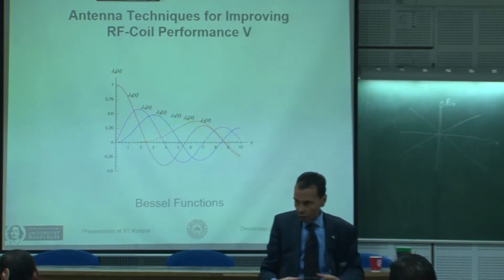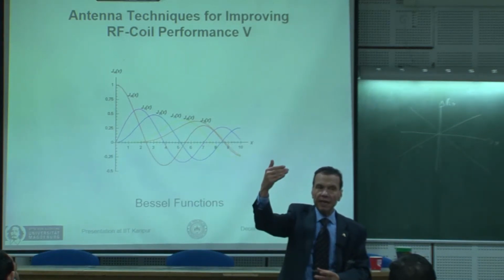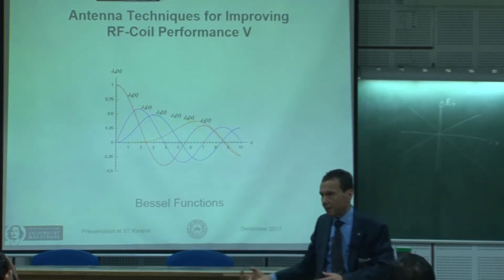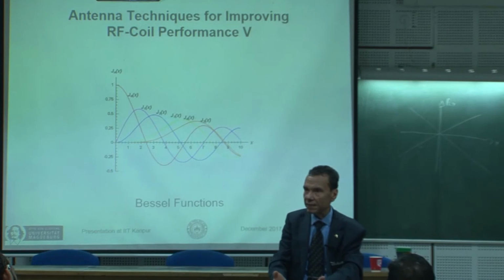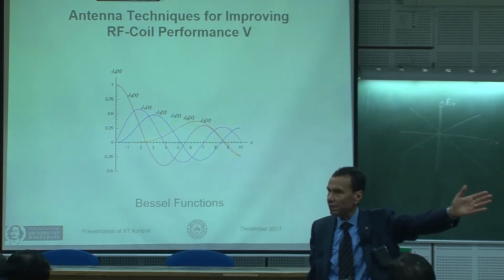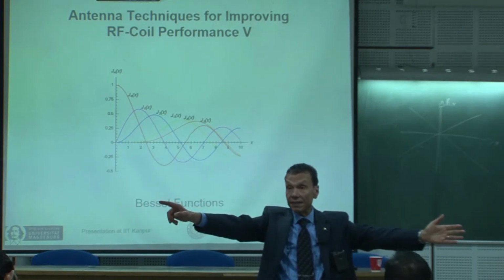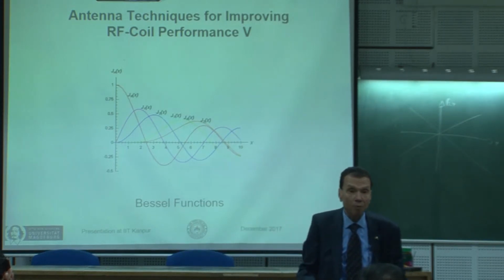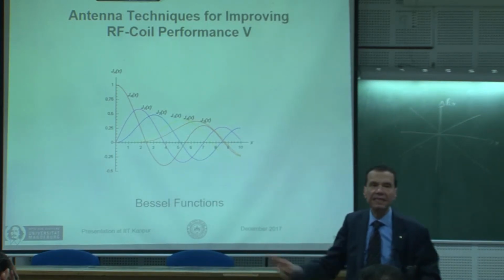If I have a network before my antenna array and take signal 1 and feed it to the elements in such a way that its beam is directed this way, and I come now with signal 2 and feed it to the same array elements with another phasing, so that signal number 2 produces a beam in this direction, and signal number 3 will produce a beam in this direction, then the same array can be used to produce multiple beams, and I can connect different signals with different beams. It's exactly the same idea here.